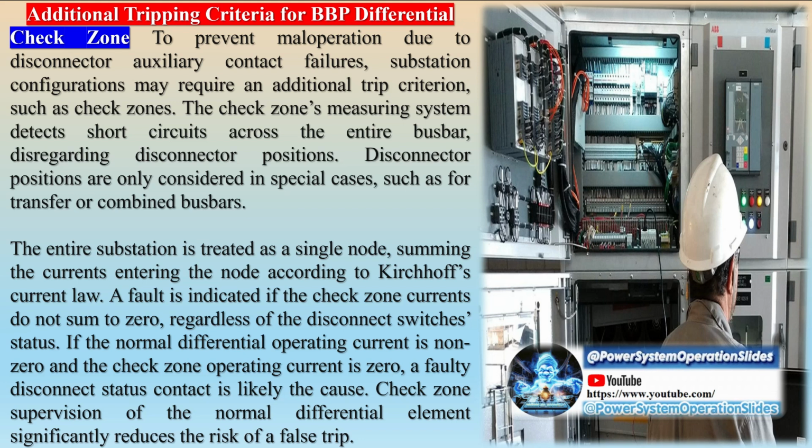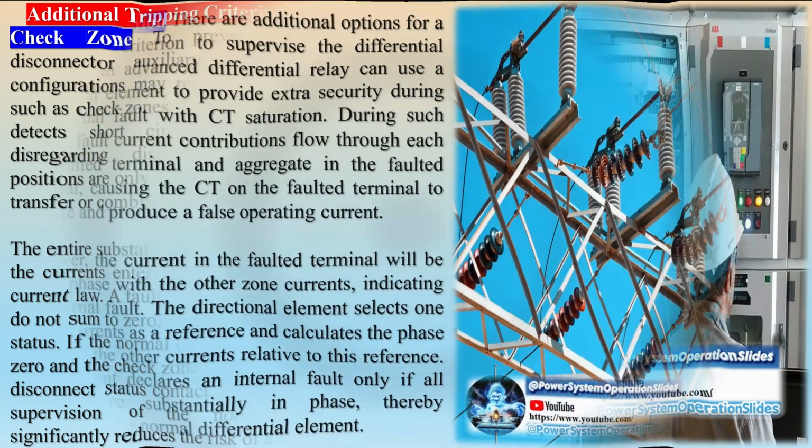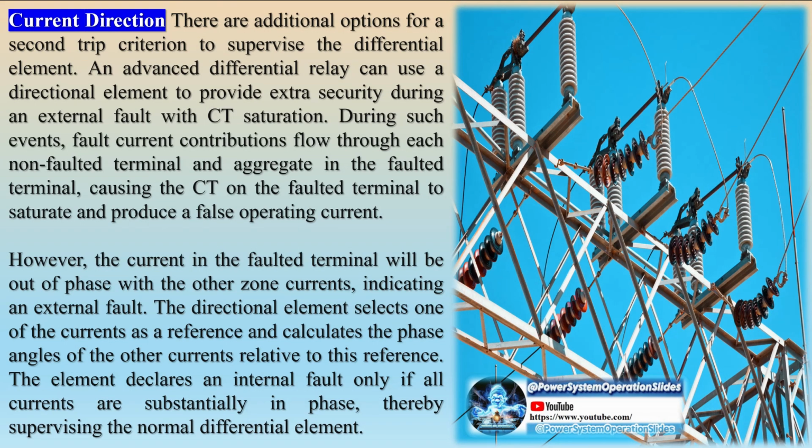While light detection is the fastest method, many systems use a combination of parameters: light, current, sound for detection. The most efficient and cost-effective method combines light and current detection. Arc flash detection system components: arc monitor unit, control unit, optical detector, current transformer. The control unit receives signals from a high-sensitivity light detector and an upstream current transformer to determine if the circuit breaker should be triggered. This process must be fast and reliable to minimize danger and damage.